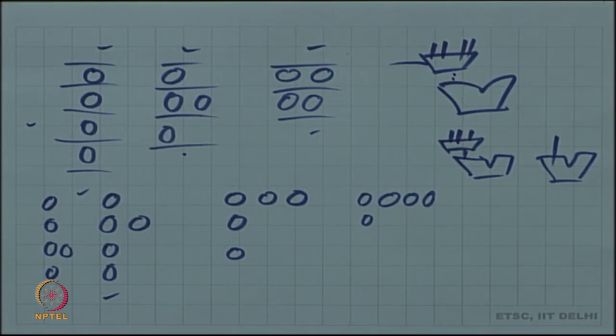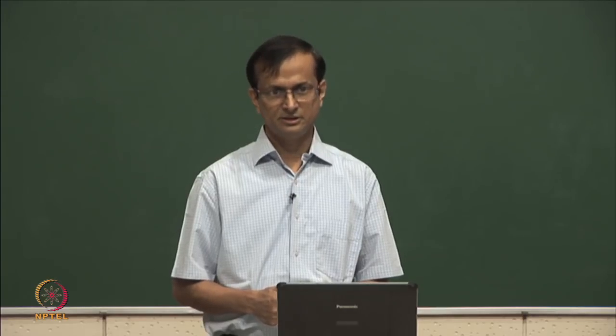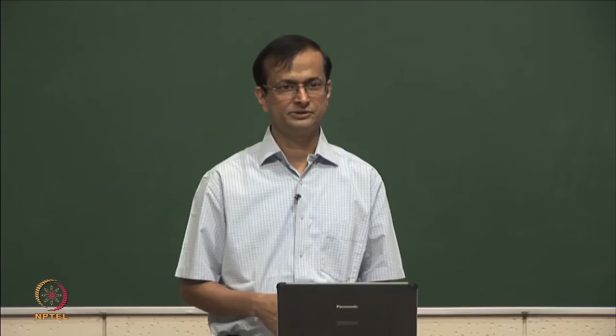Yeah, that's an interesting complication which sometimes we don't really address properly at the scheduling stage, because we are not at that level of abstraction yet. But we could. The extent of sharing that is implied by one solution versus another could be incorporated in some way in the scheduling algorithm itself. In the interest of simplification, we are doing these steps in sequence: scheduling first, then resource binding, then register allocation. But what this points out is that these decisions are interdependent. What decision you take here might make a difference later on.